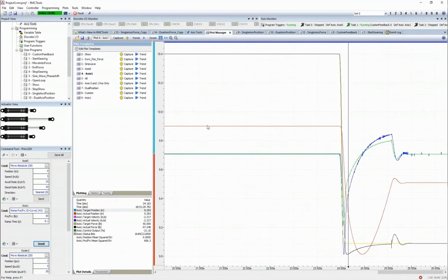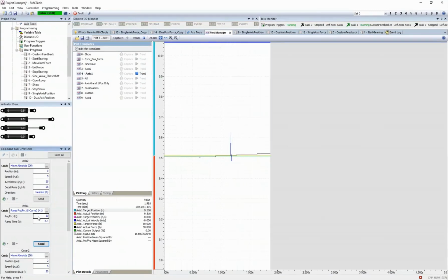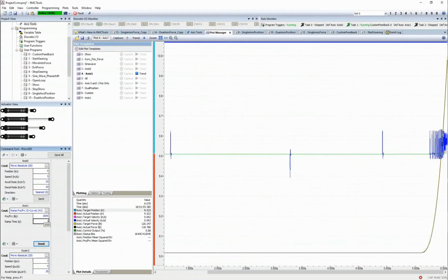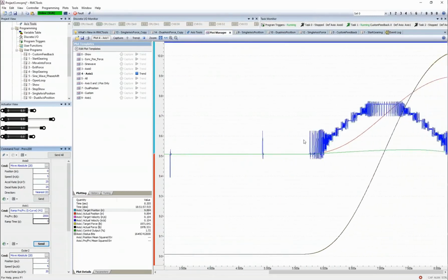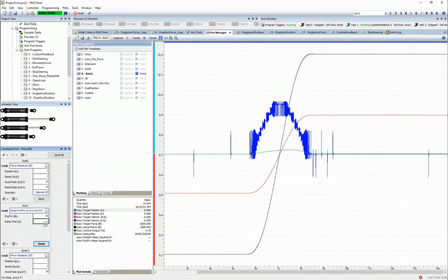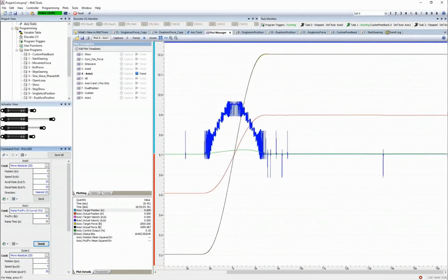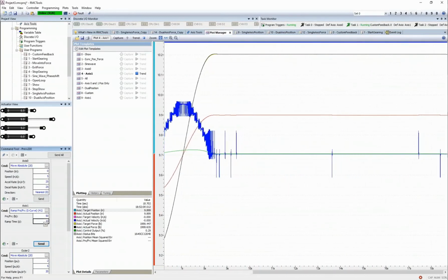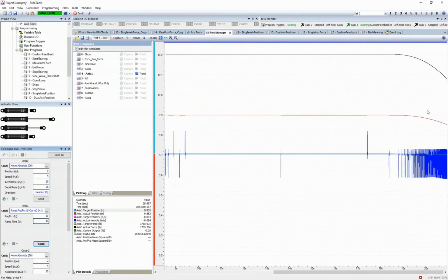Alternatively, if I wanted to disengage force and I wanted it to take a little bit longer, well, I could do something like that as well. Let me ramp back up to my 2,000 pounds here. Maybe I've got a process where I want to disengage force very slowly. I could ramp down to 50 and I could say, I want this to take 10 seconds or 100 seconds. It's whatever you want. So I'm sending this command here.